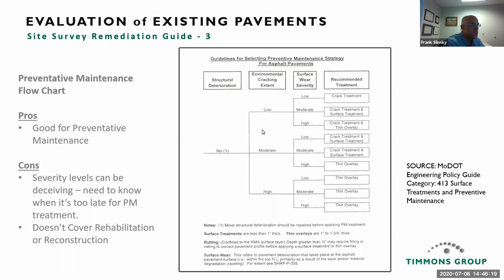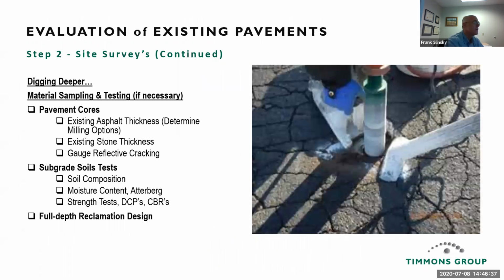But again, you look at the extent of your cracking. Say you're at moderate cracking and the surface wear is low, so then, okay, your recommended treatment: here's a crack treatment and surface treatment. Again, it's pretty basic, but it's something that can help.